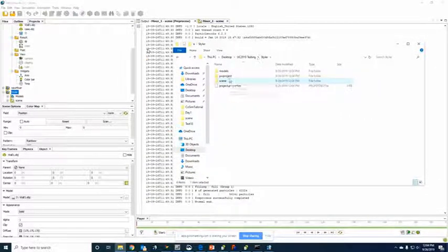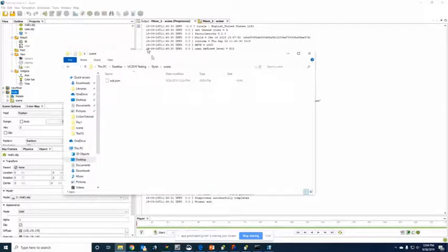What I want to do is navigate to this styler folder that was just created and go into the scene, and I actually want to copy the RecurDyn model file, the wall geometries folder, and the wall file all into this location. Doing so will make it easier, as it's important for Particleworks to be able to communicate with RecurDyn, and it knows where all these files are.